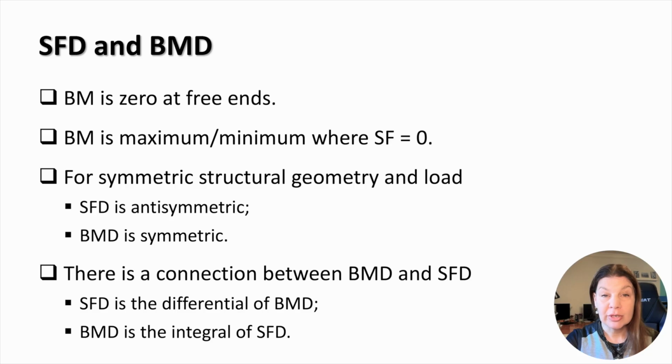If the structural geometry and loading are symmetric, the shear force diagram is antisymmetric, and the bending moment diagram is symmetric. There is a connection between the shear force diagram and the bending moment diagram. The shear force diagram is the differential of the bending moment diagram, and the bending moment diagram is the integral of the shear force diagram.